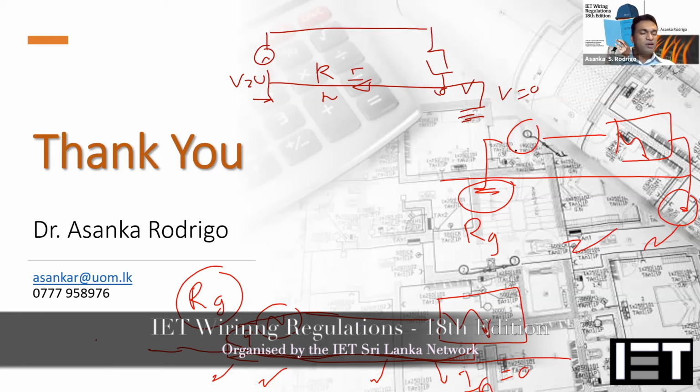Yeah. Sometimes in the building there will be certain leakage current, because theoretically there cannot be any leakage current from any equipment. If you have a leakage current, there should be a certain problem. But as I said, there can be certain types of leakage current, especially when I'm talking about the power frequency. There cannot be power frequency leakage current in any equipment. If there is a power frequency leakage current, that means there is a certain problem in the equipment.